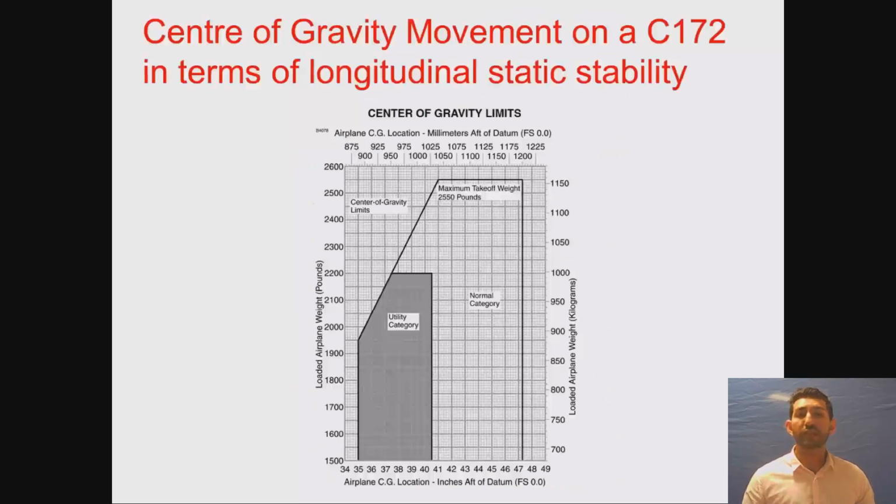Once you have that center of gravity value, remember those terms we went through earlier, static instability and statically stable. For this Cessna, more or less, this is just an approximation, but you can find that final bound at 47.25 inches behind the datum. If the center of gravity moves any further back than that, then you can consider the aircraft to be statically unstable. So you need to make sure that the center of gravity is in a location where the aircraft can fly within its design parameters.